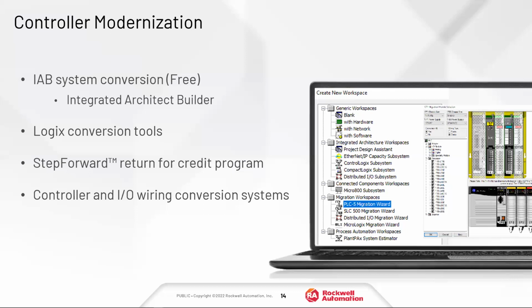The next step, which is important when you get into the configuration and the programming, is the different conversion tools that are available. Rockwell has published free utilities that assist in converting a PLC5 program to Studio 5000, for example. There's also an RSLogix 500 to 5000 migration tool that you can use for SLC migrations.